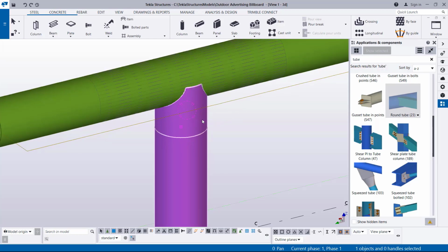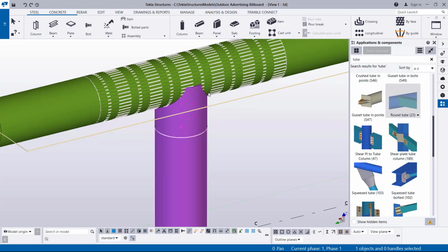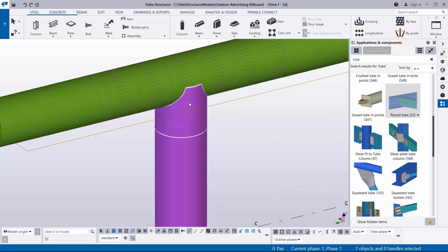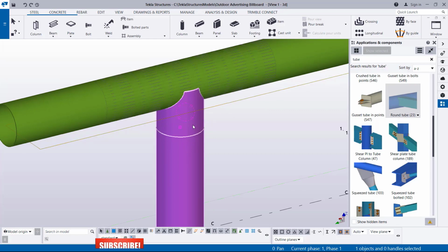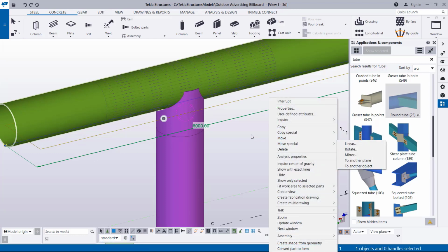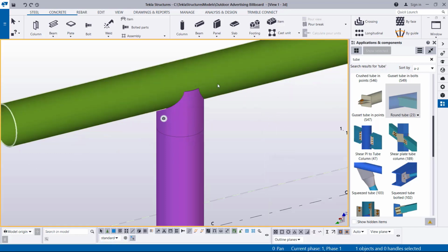So if you create a drawing, all the details will be generated on how the notching will be done, and all the measurements about the notching of this particular column to let it fit for welding, to accept the welding details between this column and this member. So let me just right click and then click redraw to remove those symbols of connection.